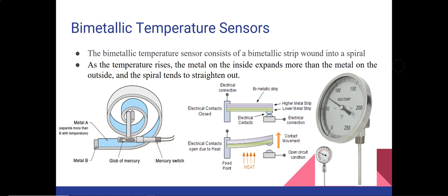switch. So what happens when the temperature increases, then this globe of mercury rotates clockwise when tube rotates past the horizontal, and then the mercury runs down to the right and completes the electrical connection between the electrodes. So that's how it works, and at the output here you can connect any electronic component, for example position detector or any indicator or a simple on-off switch, which will respond corresponding to the change in the